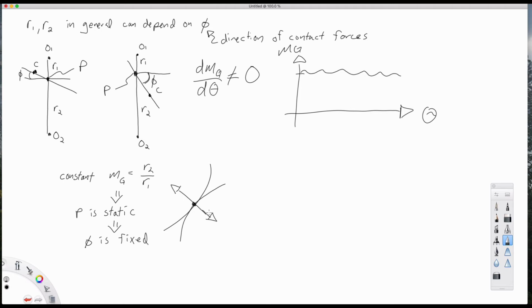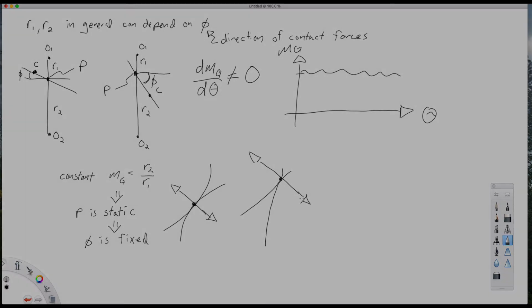And the key here is, as this contact point moves, as the gears rotate, we need the common normal to always be pointing in the same direction. So suppose we have the contact point move closer to the bottom land of the top gear and closer to the top land of the bottom gear. We need the common normal to still be pointing in the same direction with the same pressure angle. So how are we going to construct gear tooth geometry that achieves this?